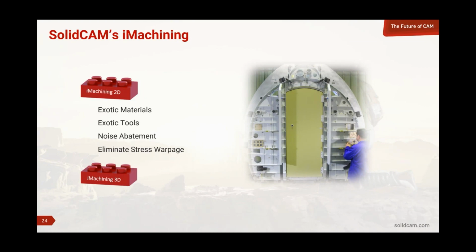Now, when we start talking about big aircraft parts like this, bulkheads and such, one of the biggest problems that we have in machining these things is the work-induced stress that we impart to that material as we're machining it. And so in traditional machining, this part would go through a whole machining scenario, remove about 95% of the base material to get to the finished part. And then when you unbolt it from the fixture, it warps like a potato chip. Well, iMachining can reduce that, significantly reduce it, and then sometimes even eliminate it.